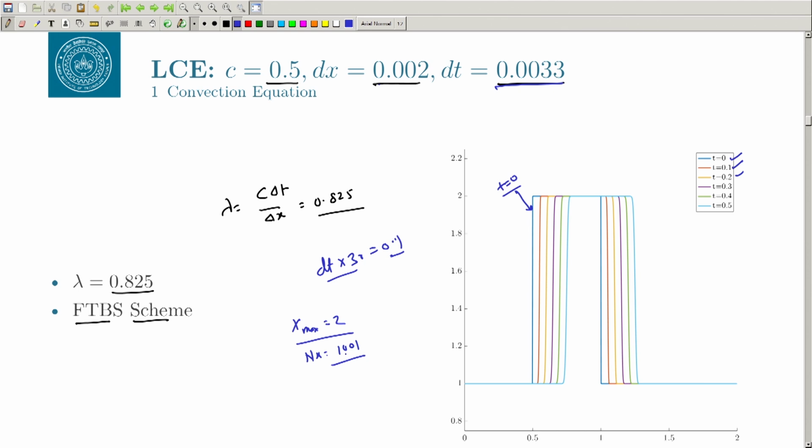So, you can see that now it is propagating, and there are certain effects that you can see if you look very closely. You had a very sharp corner here in the beginning, but as it went to the right, you can see that the sharp corner has slightly become more diffused. So, despite having no diffusion in the scheme, so there is no new, no delta squared u by delta x squared term, you still have some diffusion, you can see at these corners also. That means our scheme itself has got certain diffusion, and that is what is called the numerical diffusion.